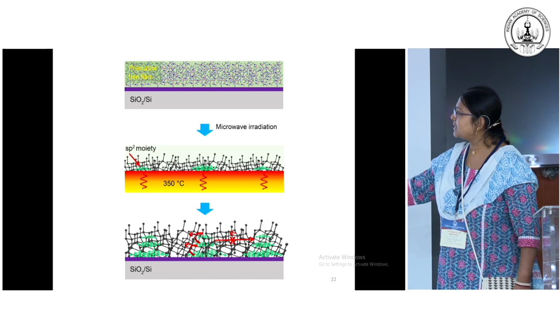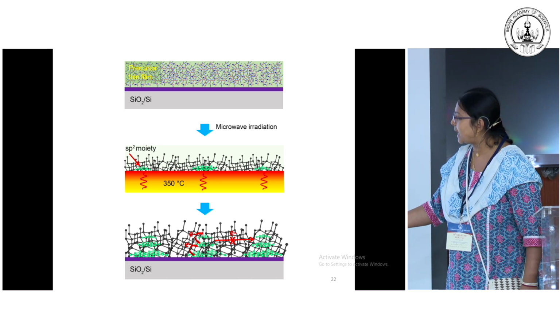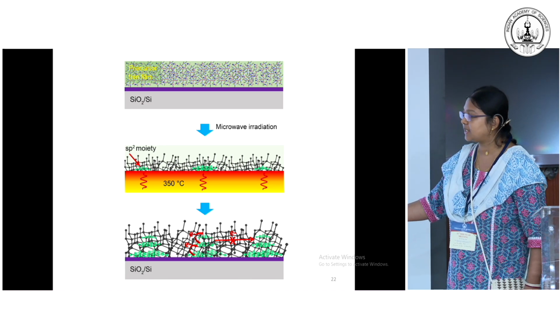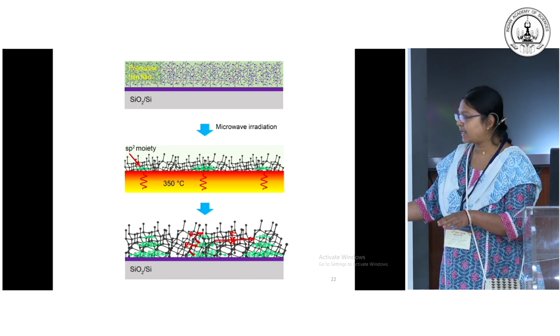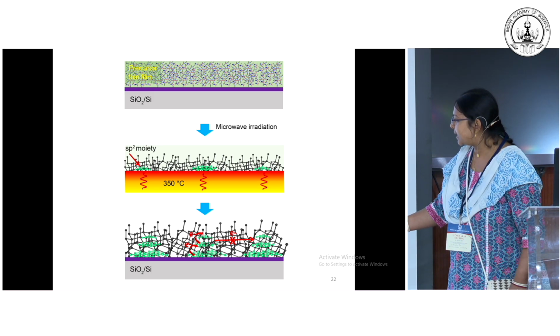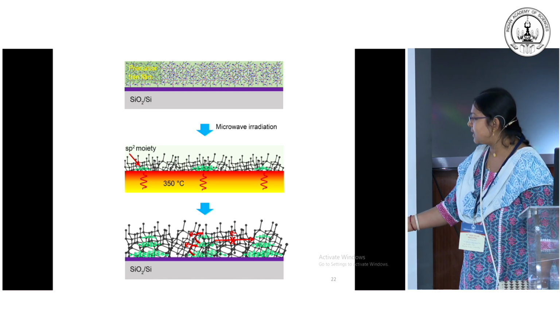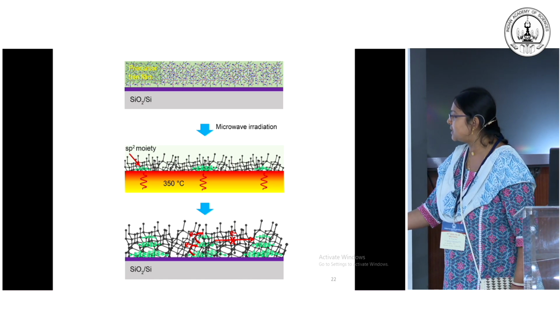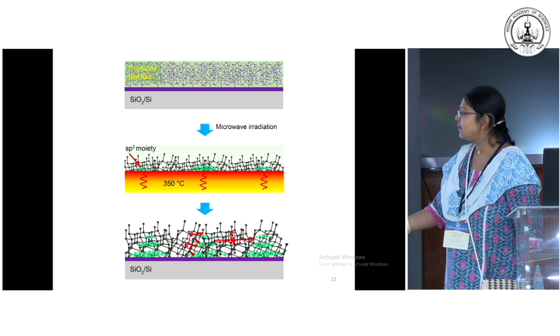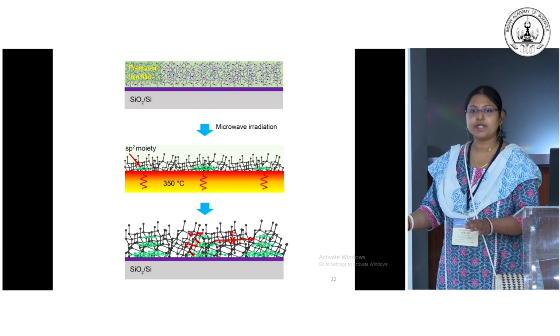So this is becoming very much conducting, and gradually as it goes up, the distance from the substrate becomes higher, and the extent of graphitization decreases. So there is some gap, we can see that there is some gap. So electrical conduction is being limited in the lateral direction, but in the vertical direction it is being facilitated, and also it is very much thickness dependent. Graphitic film is also not so conducting in the perpendicular direction because of the van der Waals gap.